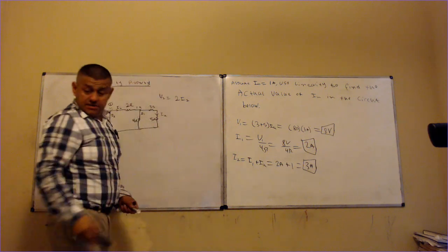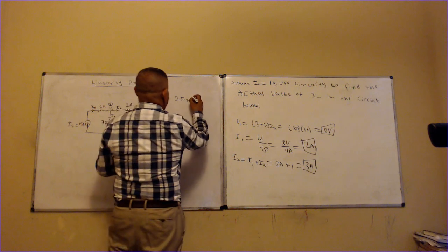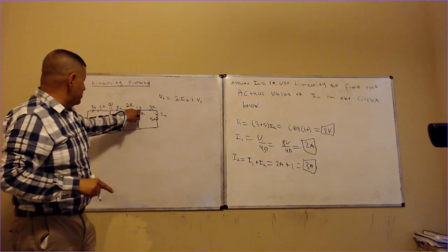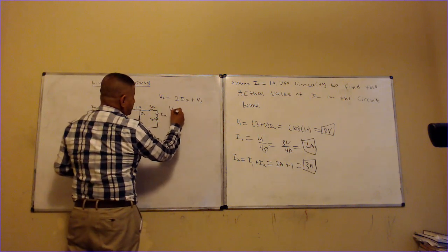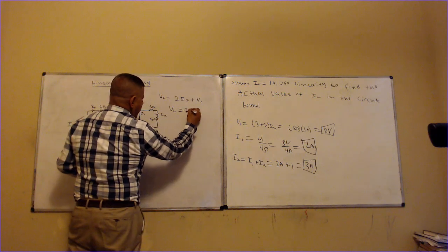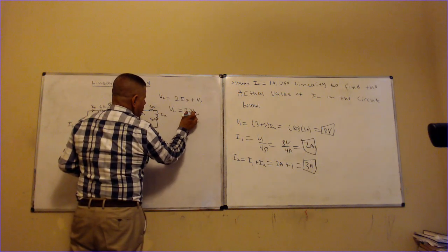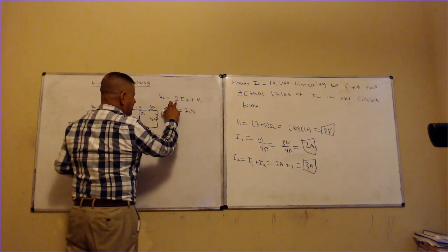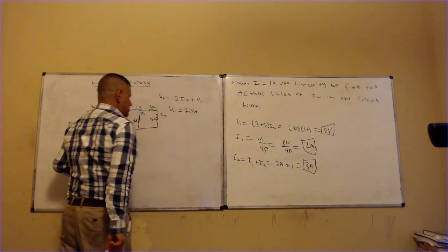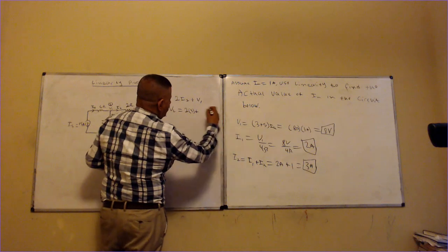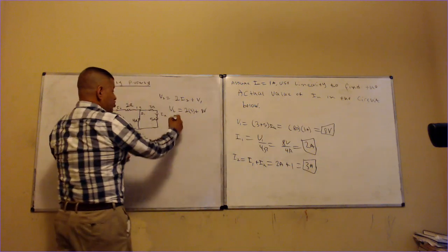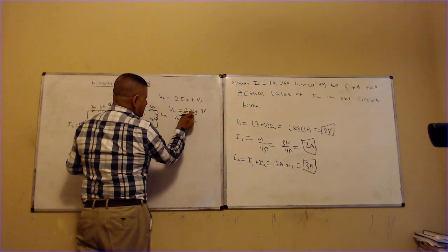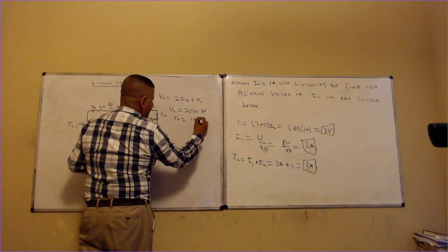So basically, what I can do is plus B1. What was B1? B1 was this guy. So V2 is equal to 2 times 3, right? The current I2 is 3, and that resistor is 2, plus V1, which is 8 volts. So when I add those, I get V2 is equal to 6, 6 plus 8 is equal to 14 volts.